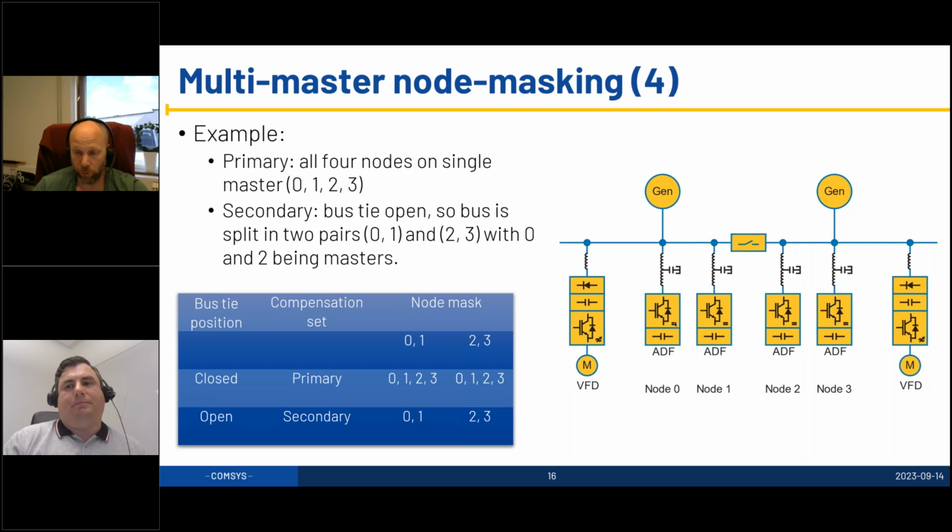However, if you have a problem with that, of course, you now have the ability to use sensorless control with multimaster, or you can use impedance control, and you don't even have to use multimaster. So now you have much more options to actually get rid of the CTs if they are a problem. And I know they can be very hard to practically install.